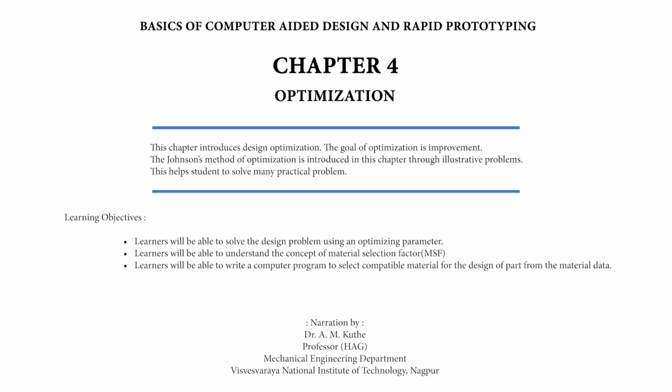The variables are classified into three categories, namely number 1 functional, number 2 limiting, number 3 free. Functional variables. The variables which represent the functionality of the part are called functional variables. The parameters of which value is given in the problem are functional variables. Thus, in this type of problem, F, L, Fs are functional variables.